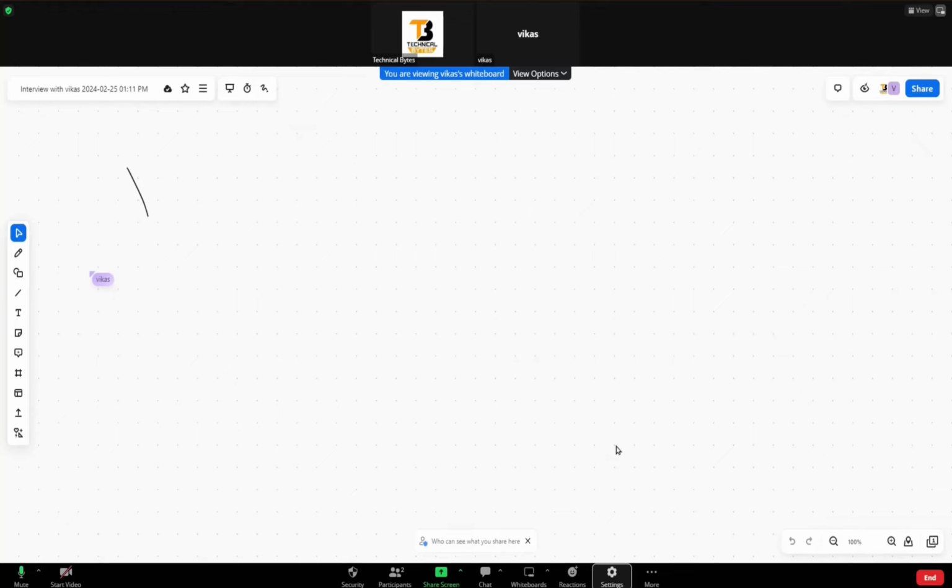So after that time, your output will be stable, you are saying. Yes. Now this output is applied to other flip flops, those flip flops are synchronous with the LSB flip flop. Can you tell me what will be the maximum frequency of operation for your design? That will be the TCQ of all these three flip flops, the NOT gates, and then setup time of this synchronous flip flop. You understood why, right? Yes, sir. Very good.